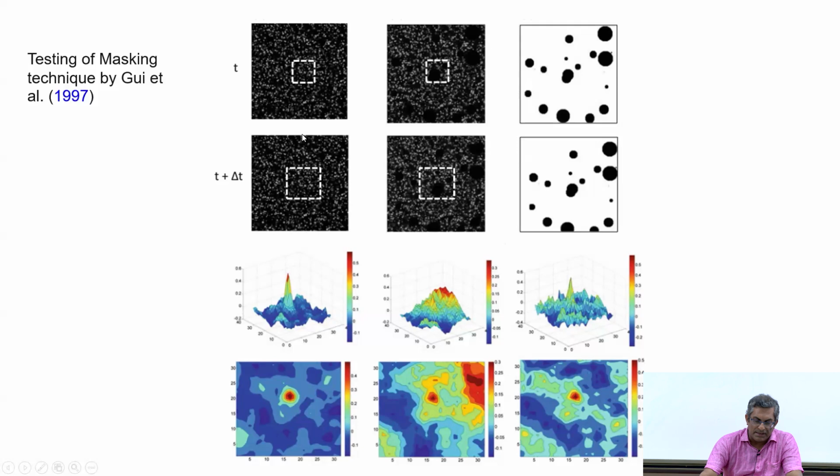So, for instance, this is the ideal case and this is the non-ideal case. Here we have removed some particles that possibly you won't be able to see here. Now if you process this image, you get a sharp correlation peak as shown here. So this gives you a good velocity vector field.